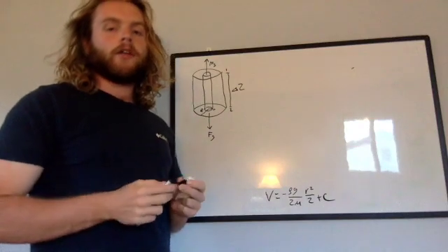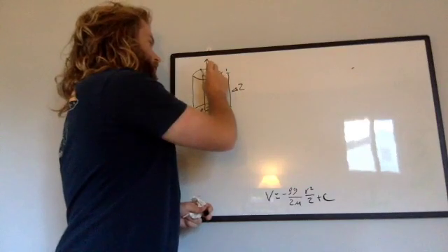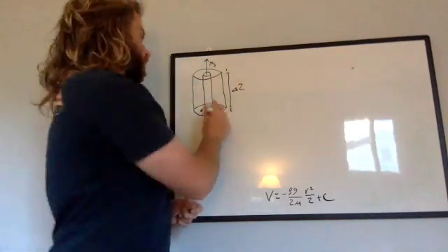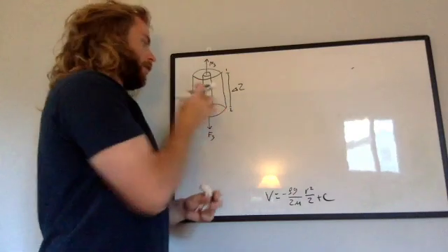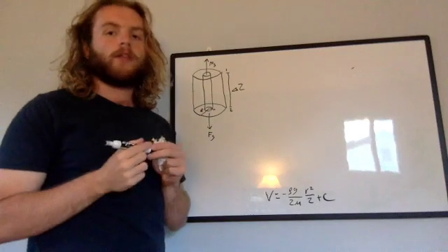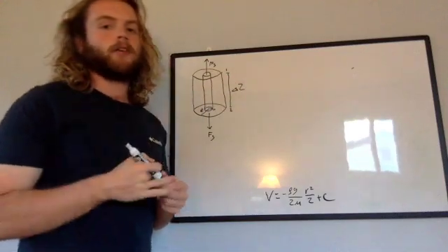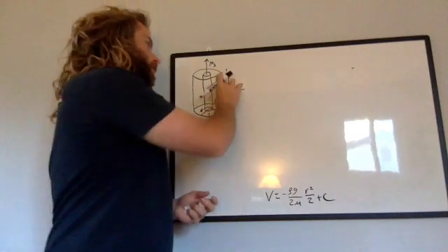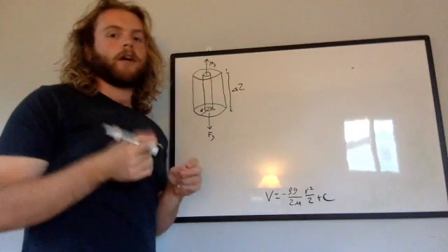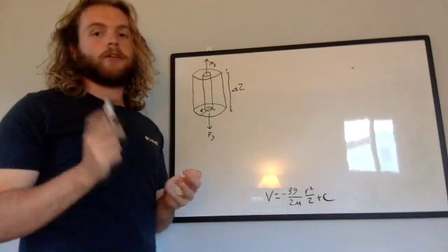And we know that when the radius of this sample volume, when that little r is all the way out to our big R over here, meaning that it is the full radius of the pipe, we know that the velocity is going to be equal to 0 due to the no-slip boundary condition, right? Out here by the very edge of the pipe where the pipe is not moving, we know the velocity of the fluid is not going to be moving either due to the no-slip boundary condition.